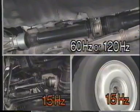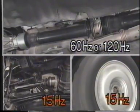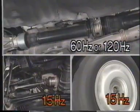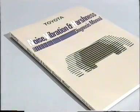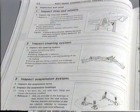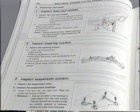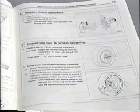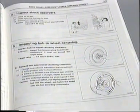Now, we will return to troubleshooting the problem of vibration at 15 Hertz. We will start with inspecting the tires, because tires often cause body shake at high speeds. We will refer to the NVH diagnosis manual as we inspect the tires. Before we begin the inspection of the tires, we must check the tires and wheels visually, the steering linkage, the suspension system, and other related components.